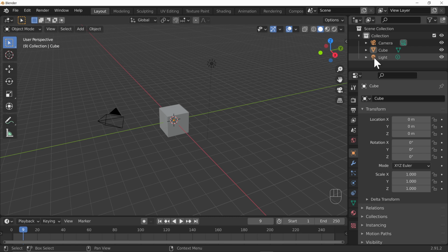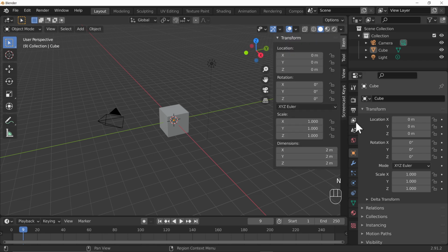any difference at all. Let's have a look at the properties panel, which in this particular case matches the object properties that we can see over on the right hand side here. So we've got a series of boxes that seem to all be the same, apart from there's no dimensions over here on the right. And indeed, if we go ahead and click and drag or type a number into one of these fields, it updates elsewhere. So typing numbers into either the location, the rotation and the scale enable us to be very precise about the actual value that we want.